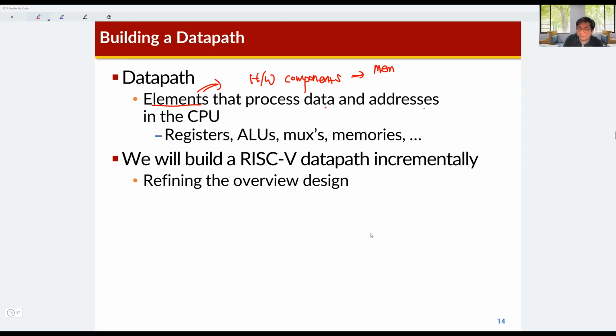such as memory, like instruction memory and data memory. Also the register file, because the register file receives the register number, and data is stored in and read from the register file. Also the ALU, which receives two operands and generates an output based on the selected operation.